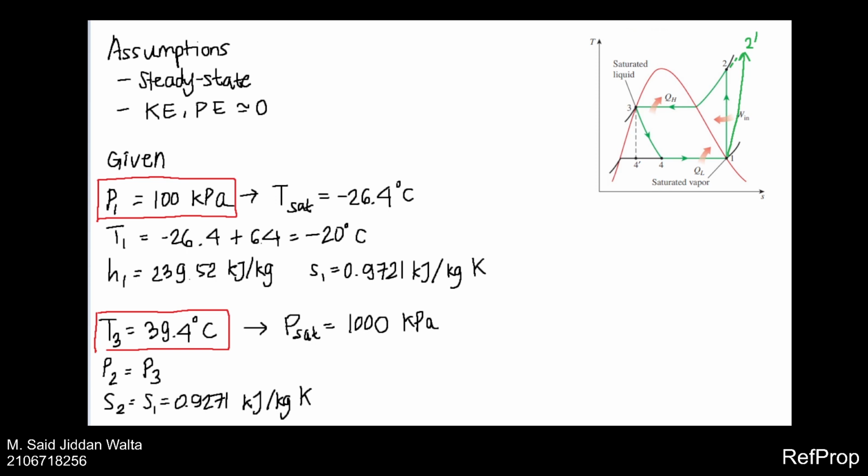But here we put the original point 2 at the top as if it were completely isentropic, while the 2 prime is the actual cycle. So for the purpose of enthalpy and entropy, the point shown completely above in the compression process is the 2s, or the 2 in the completely isentropic position, while the 2 prime is the 2a, or 2 actual.